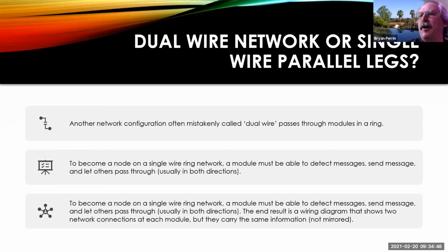And that's very common. The daisy chain is very common, and that's helpful because if I lost communication to three modules and I look at the wiring schematic and the three modules, this module, the one that's daisy chained after, and the one that's daisy chained after to the end of the chain, I can't talk to the three. Where's my problem? It's the wiring between the module I can't talk to and the one I can, or that module itself. So, and I got some pictures coming up, if you guys aren't following me.